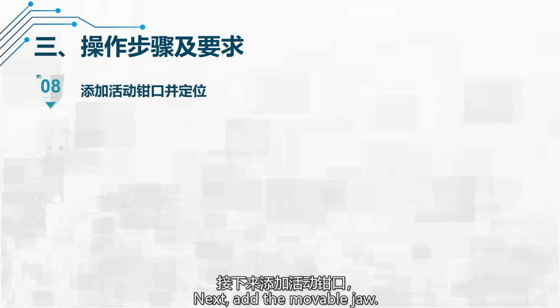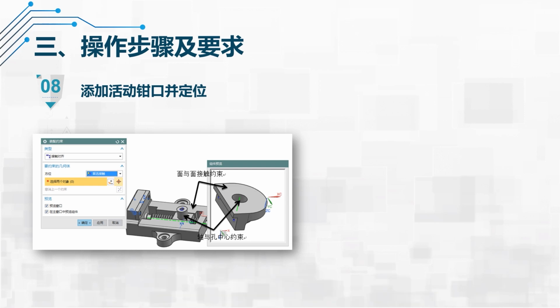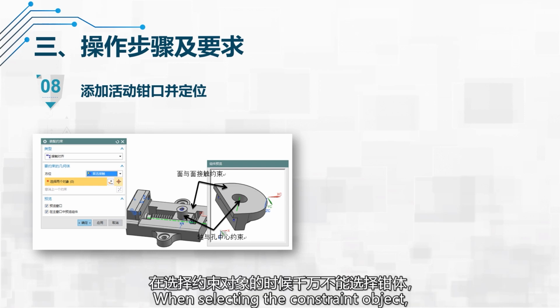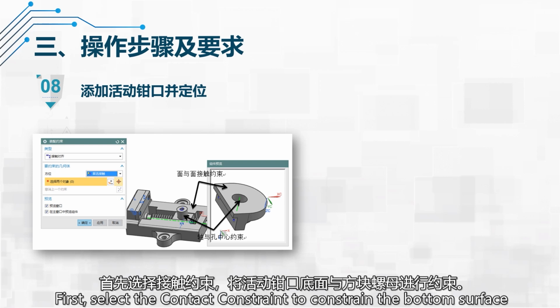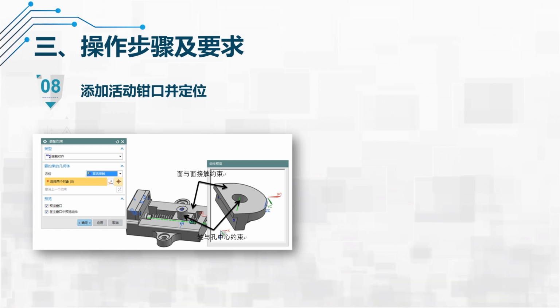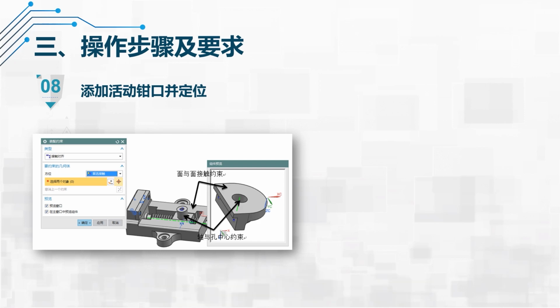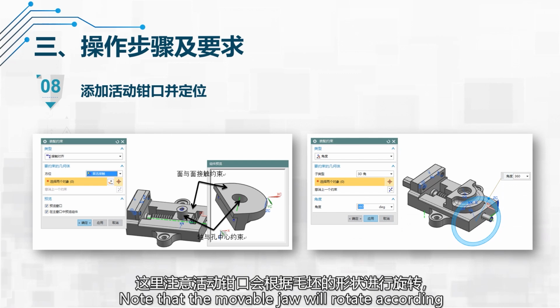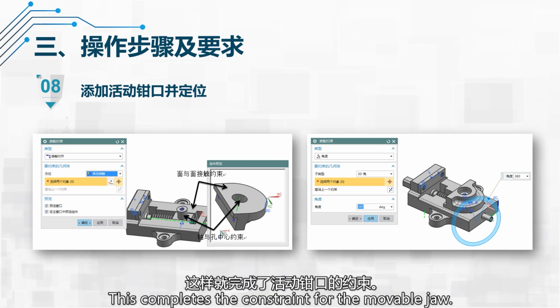Next, add the movable jaw. The jaw component moves with the square nut during assembly. When selecting the constraint object, do not choose the Vise body, otherwise it won't move with the square nut. First, select the contact constraint to constrain the bottom surface of the movable jaw to the square nut. Then constrain the center axis of the jaw to the axis of the square nut. Note that the movable jaw will rotate according to the shape of the workpiece, so an angle constraint must be applied. This completes the constraint for the movable jaw.